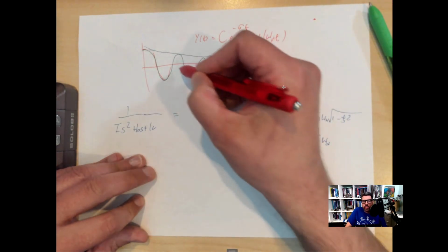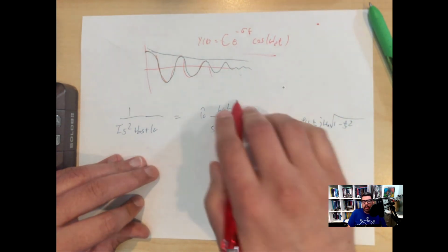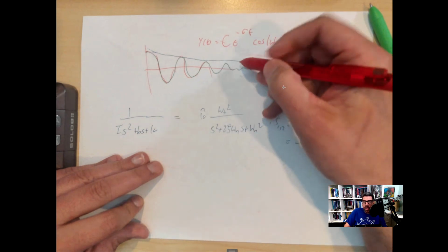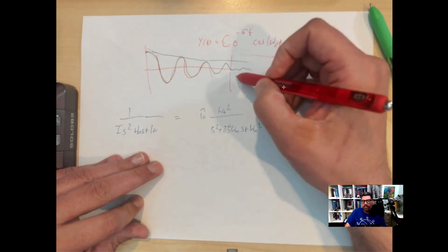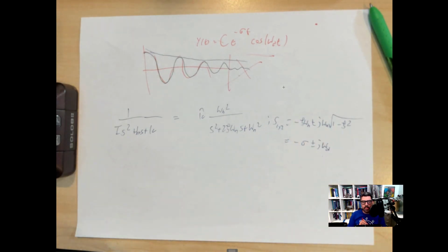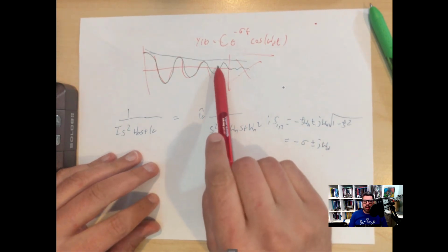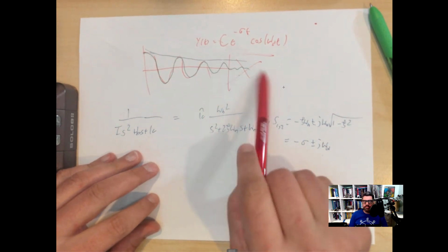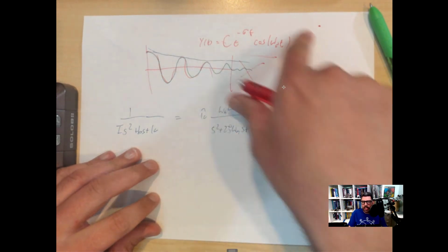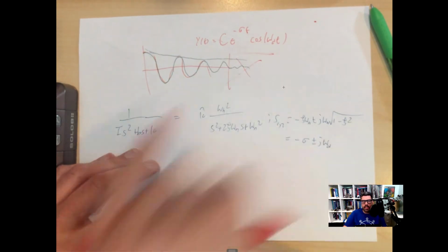That's what we're going to do. So you're going to fit the best of that function on this signal. Now, be careful at the end. I would cut off at some point, X out some of this. The end stuff gets nonlinear because of stiction, because of Coulomb friction. So that Coulomb friction is nonlinear. So be careful. The velocity starts to get small here, and it starts to become garbage from a linear system perspective. So you want to get a good number of periods, but not at the end.